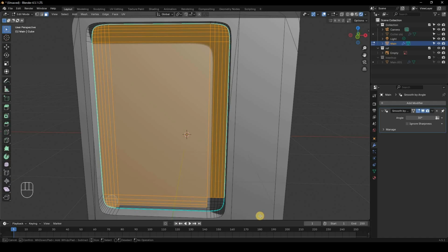These faces, sorry, not vertices. I'll select all of these faces. Okay, and if you accidentally select something that you didn't want to select, let's just say I accidentally selected this, I can always Shift and click and then deselect it. And I can obviously use the mouse scroll wheel to increase or decrease my radius, and then I can right click to get rid of the circle selection.